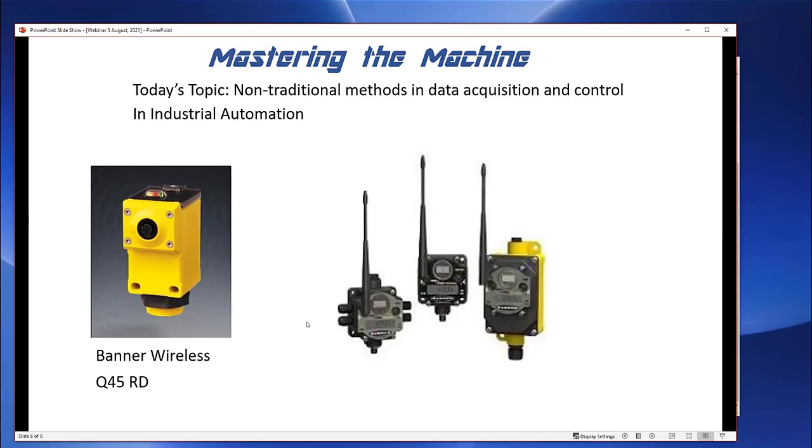Because as we've talked about here before, the languages that are spoke by PLCs and data acquisition systems are pretty specific, right? So Allen Bradley's Ethernet IP, there's things like Modbus that almost everybody uses, but it does need to be pretty fast, right? Because I'm counting things anywhere from 3 or 4 per second, things coming down the line. I need to be able to pick up transitions that fast.